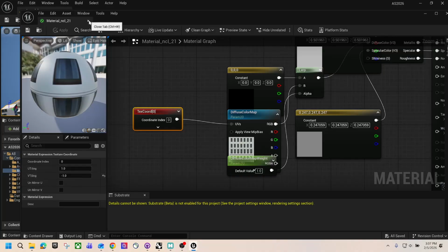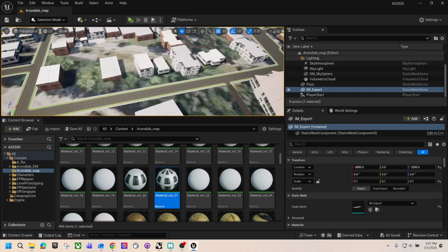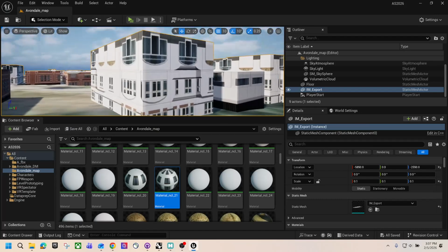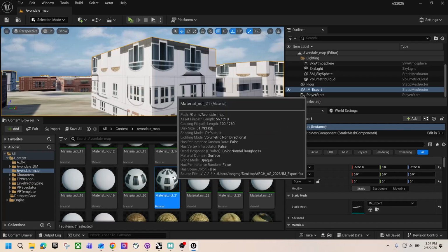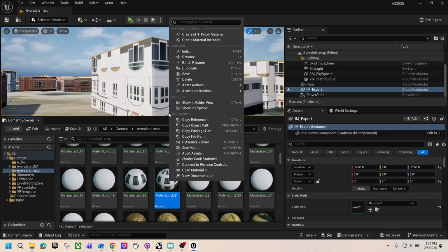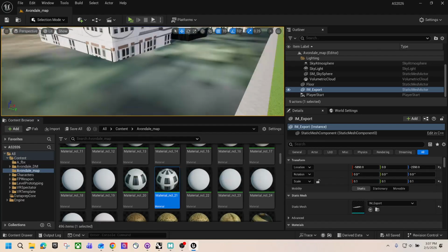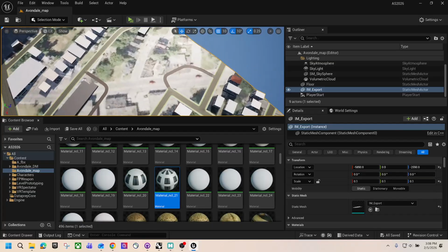But here's a problem. If I look at the building, for instance, if I zoom in a little bit, you can see the building is actually upside down, right? Because Unreal doesn't really understand what the -1 means. So you can't really use negative directly in Unreal, unfortunately. The same problem you can see from the terrain on the ground. The terrain model definitely is flipped, right?